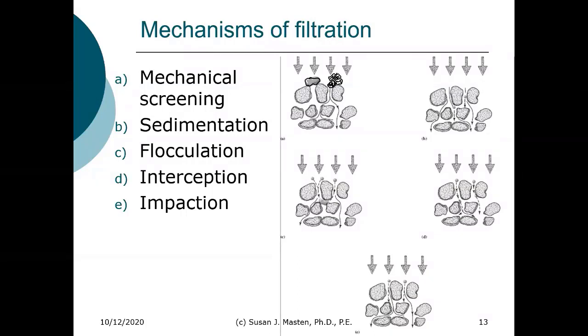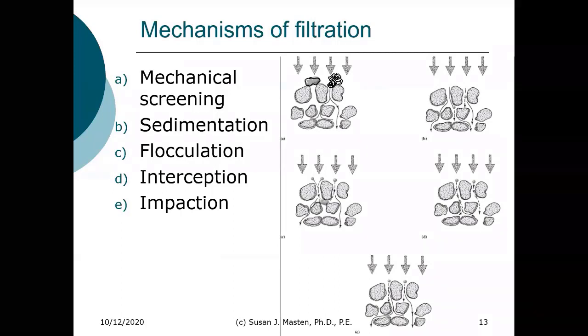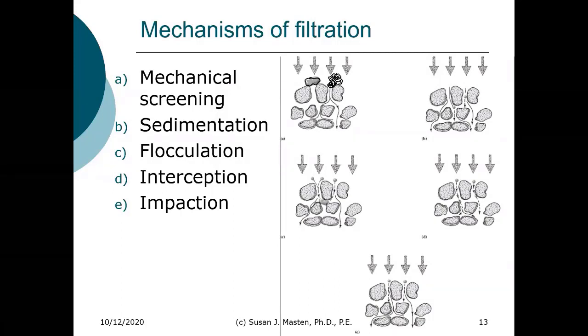We also talk about sedimentation. Here, the mass of the particle and the diameter of the particles are large enough that the particle actually settles. So this is moving by settling, and it settles, deposits on a particle. You can see it's smaller than the pore space, but it deposits on that particle and it's removed by settling.